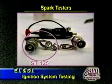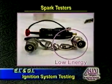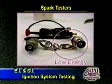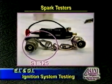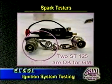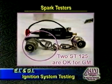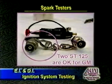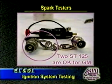The kV spark tester on your right is what we call low energy. There is a need for those. For example, for those technicians that will take 2 of the ST125 spark testers to double stress a GM Type 1 and Type 2 coil pack, that's great. If you take 2 ST125s and clamp them together, obviously that's a kV value of 50,000 volts. The GM Type 1 and Type 2 coil packs have the kV potential to easily fire 2 ST125s clamped together.